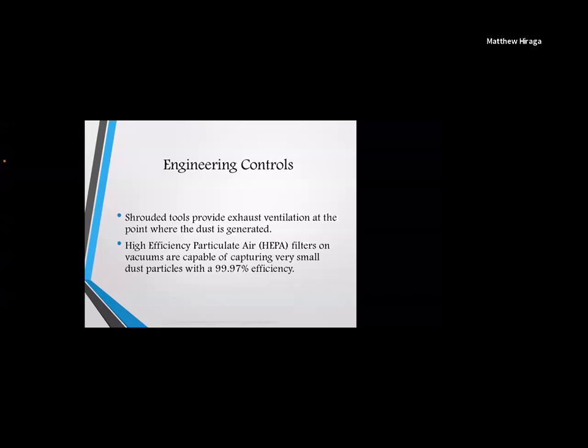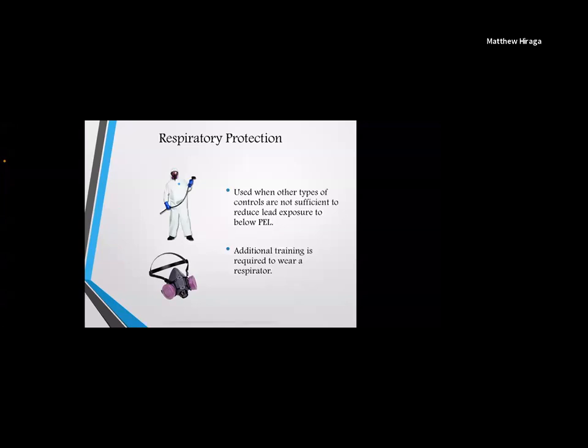And then here's some examples of the PPE you would be using, right? Whether it be respirators. Respirators cannot be used without a physical, basically saying that you are fit, right? They do pulmonary testing, saying this person can handle restricted breathing, so they can wear a respirator. And then you have to have an annual fit test.